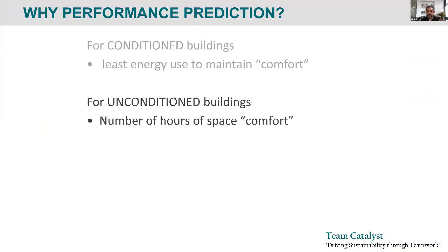So you might set a temperature band, and you might set a relative humidity band, and that's what the air conditioning system meets. And then your interest in using energy simulation is to say, how can I use the least amount of energy, and therefore the least amount of greenhouse gas emissions, to maintain this comfort? How can my air conditioning system and my building envelope do this together?